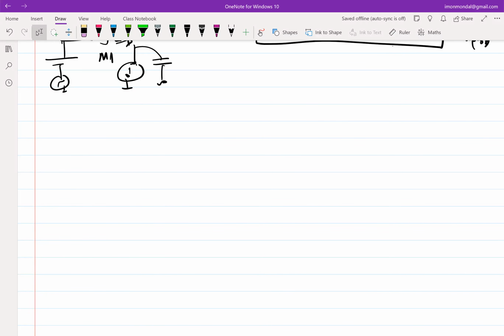You can make decently behaving current sources by doing some funky stuff. But let's assume that a current source is available, and we are trying to mirror the current from one branch to another. The question we are asking is: what is the best way to mirror? Till now, we have assumed that if you just make the VGS the same and W by L the same, then the mirroring is perfect. But in essence, it's not, and we know why. For example, let's say I have a current mirror.